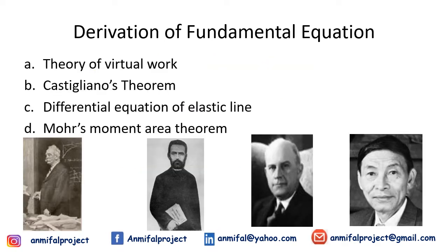Based on the fundamental equations, we have the theory of virtual work, Castigliano's theorem, differential equation of the elastic line, Mohr's moment area theorem, and the Kani and Takabeya methods for structures analysis. Of course, they use the parameters correspondingly: the stiffness of the member, the modulus of elasticity, the moment of inertia, slope and deflections, the moment rotations, and the moment distribution itself.